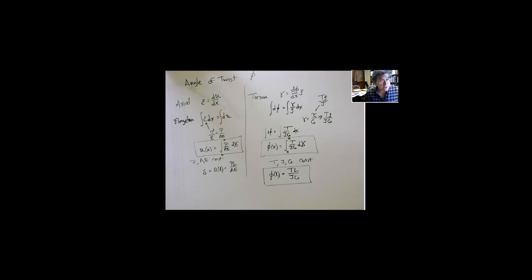So that's the angular twist. And, again, if you memorize this equation, you can see it's the same equation. Instead of P, we have the torque, L is still the length, J is the geometric factor for torsion, and then since we're dealing with shears, we have G, the modulus of rigidity, as opposed to Young's modulus.